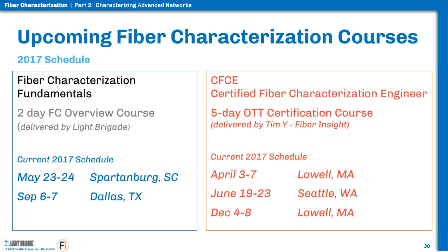Okay, thank you. For another question, do you recommend 100% testing on the fiber in a cable in terms of CD and PMD measurements? Well, again, that's difficult to say. If it were new fiber going in, I would probably recommend a baseline of all fibers that are going in. Sometimes you're only dealing with 2 fibers at a time.